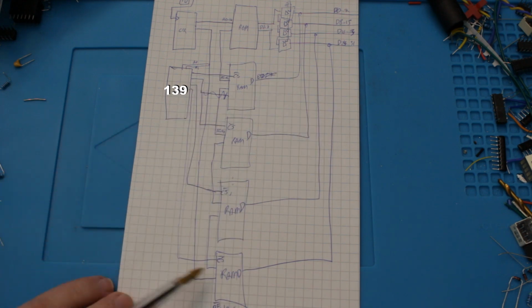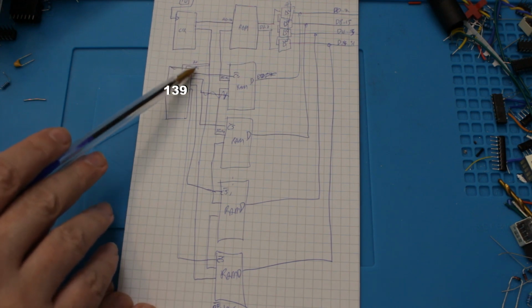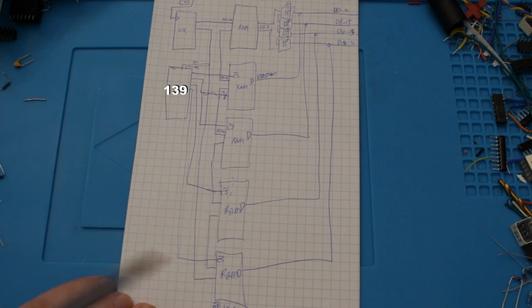Then all 4 of these RAM chips are in write mode, so that they're receiving data from the data bus. The addresses all get piped in just like they were coming from the CPU, and the 137 decides based on the low bits of the address bus which of these RAM chips needs to be activated. So essentially what we're doing on startup here is reading the entire ROM and writing it into RAM.